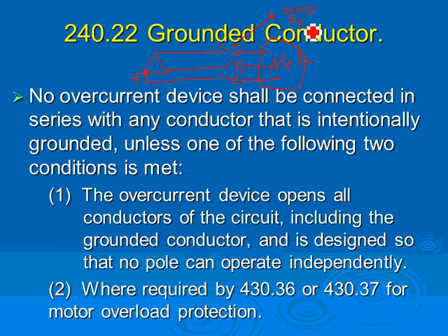Now you don't have a backup for your overload. If that fuse is to malfunction, you burn your equipment. If your overload malfunctions, you still have a backup overload protection through the fuse or circuit breaker. That's the only place you can put a fuse in.